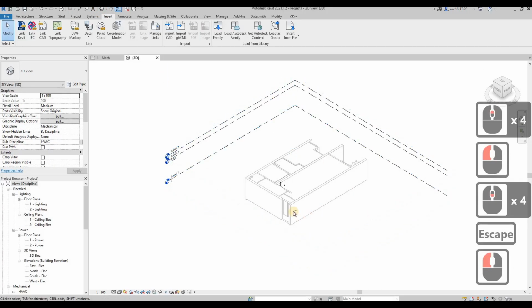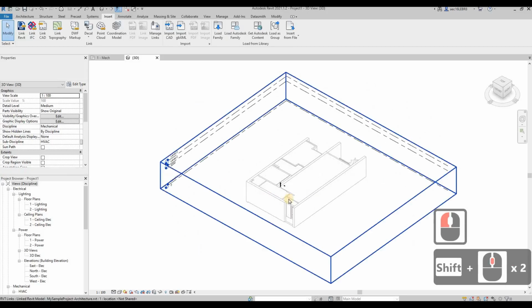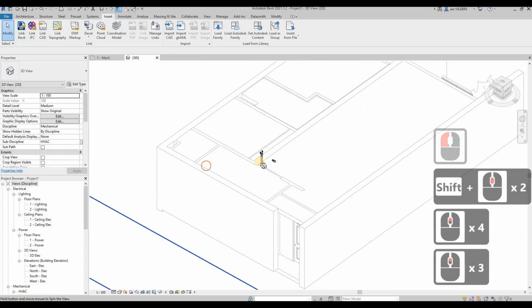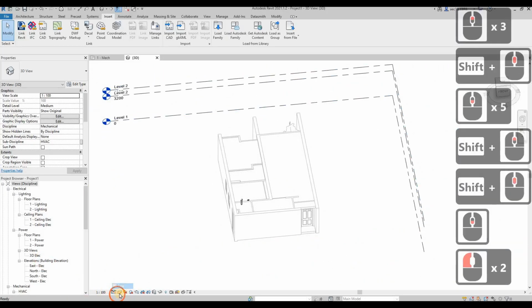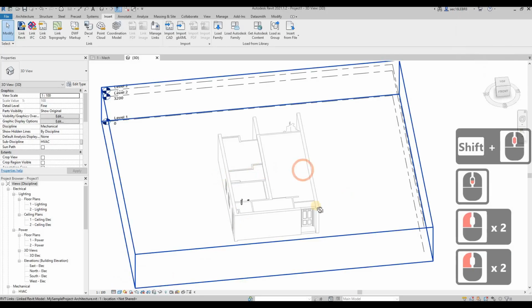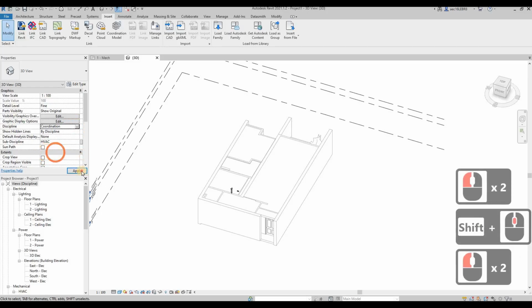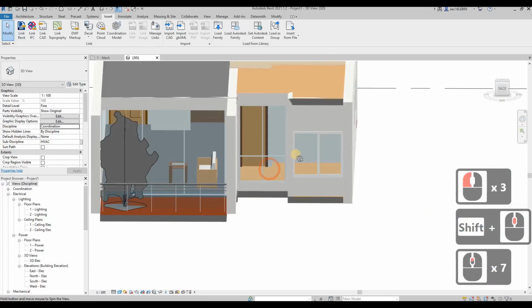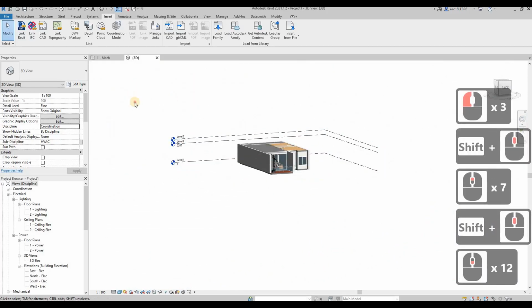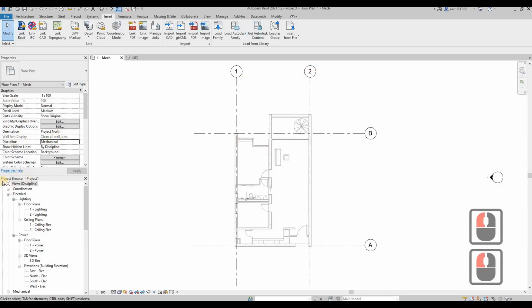So click here. You can have your view of your architecture view, and of course the view is slightly different compared to the architecture view. If you want to configure your own view, you can always do so. So this is under mechanical view. If you change to coordination, it will show more completely the entire project, okay? So we just leave it here. This is the browser organization for this MEP services.